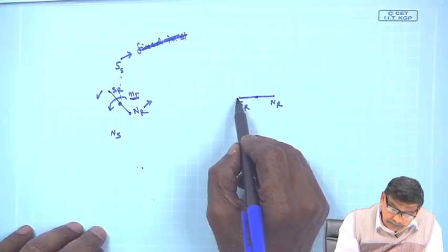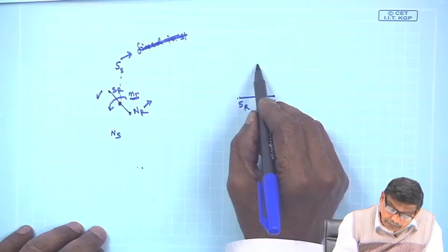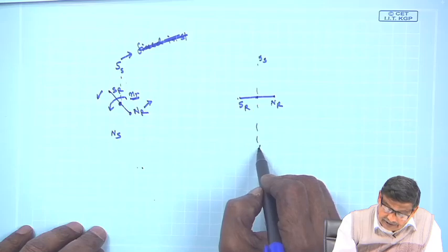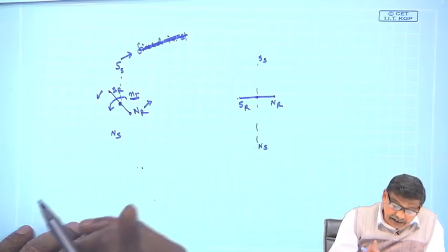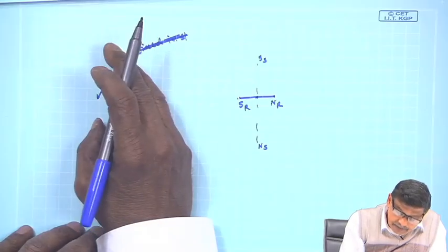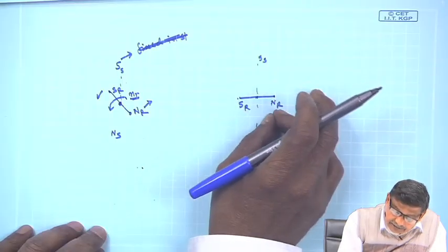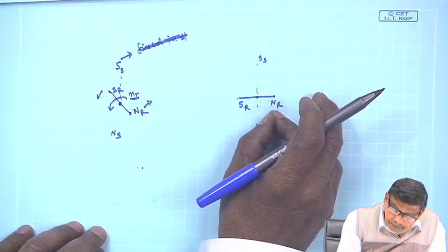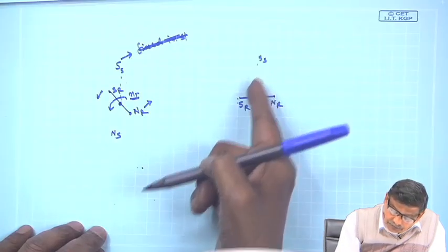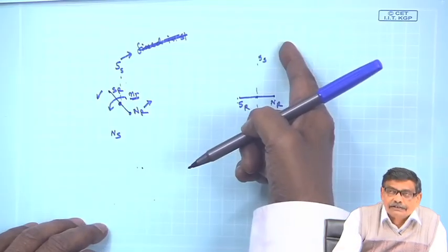Suppose the rotor poles come here, and the stator poles, it was earlier here SS NS, and if I demand whatever torque it was producing at this instant of time, some time elapses, the rotor poles come here SR NR, then obviously once again the same torque exists here, but the magnitude of the torque depends upon how far this SR is from SS.